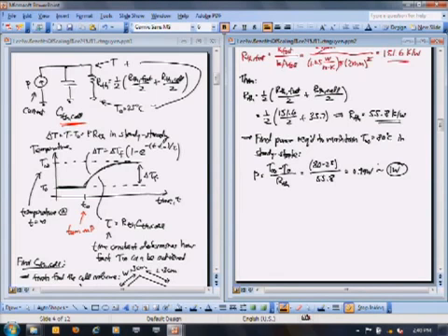All right, so next thing we want to do is how fast can we get it to temperature, so let's just find the time constant. Okay, well, we know the time constant, very simple formula. That's RTH times the thermal capacitance of the cell. And if you plug the numbers in for what we have, you end up with 24 minutes for this particular cell. Okay, so it's 24 minutes for tau. How long does it take for something to warm up? Well, in general, it takes about 3 time constants, so 3 tau, to reach steady state.